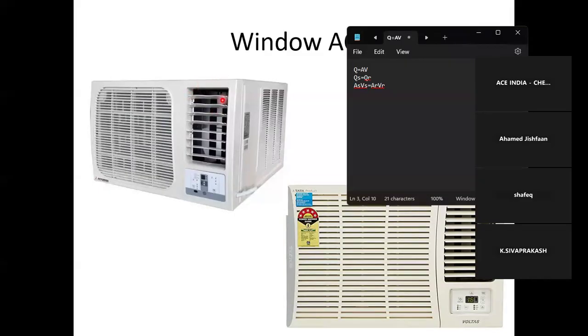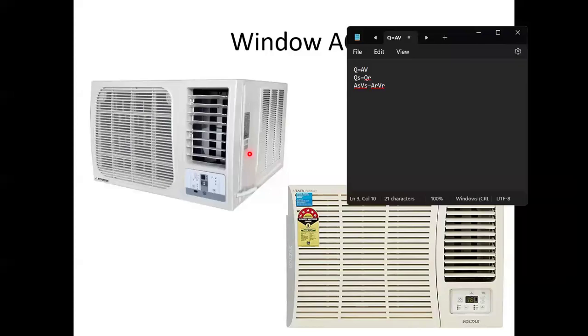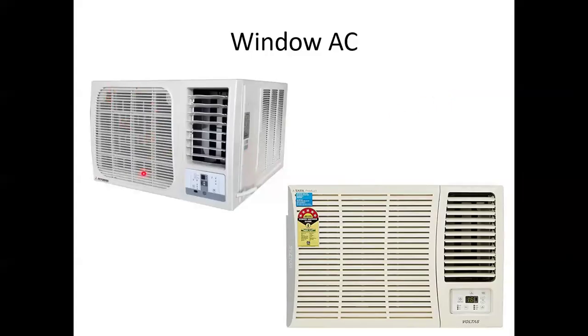If you reduce the area at the supply, the air can displace more distance, isn't it? Whereas in the case of return, we don't need velocities. We must ensure that the entire air quantity is entered into the machine again. For that, we need more area to accommodate the returning air, isn't it? So this is the concept behind the area differences between supply and return. That's why we placed our air filters right in front of this one itself.